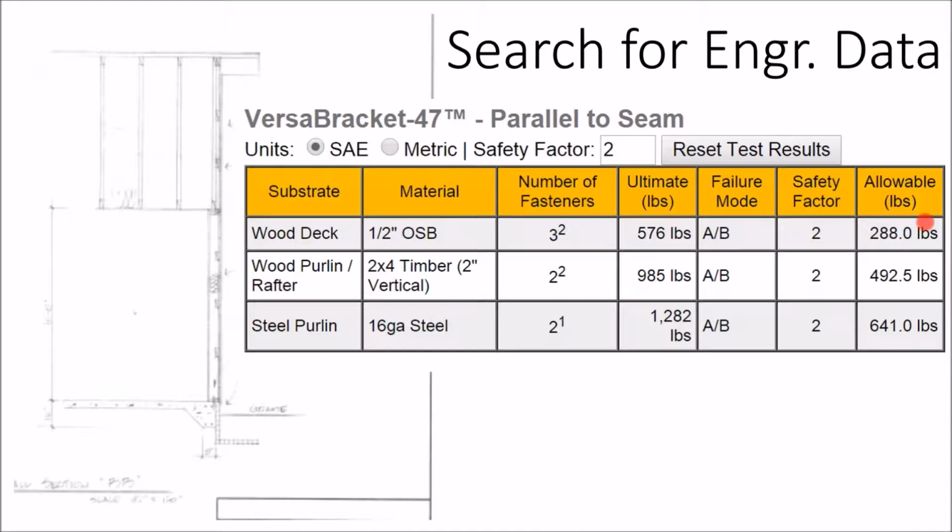If you're using a decking-based racking system and you're going to the very corner of the building, you might have a gust of wind come through and pull that module up and out of the rooftop. But if you stick to zone 1 and zone 2, you should be within the right safety factor. So taking the time to go through structural assessment can add more flexibility into what racking system you're going to use.